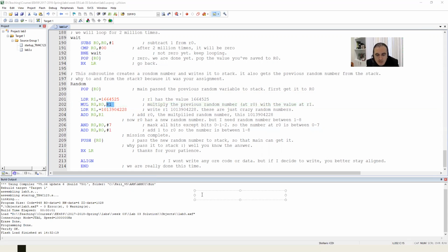What the operation I'm doing is, I'll try to put it in simple terms for you. Imagine I had a value in R0. I'm getting R0 times R1, which is a constant, okay? And writing it to R0. So this value is being written to R0 now. And this value is actually 16. Okay, then I'm summing this value with, that's the operation, can you see that? And I'm writing it to R0.